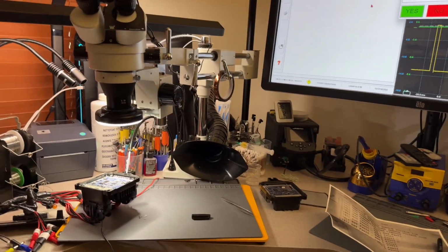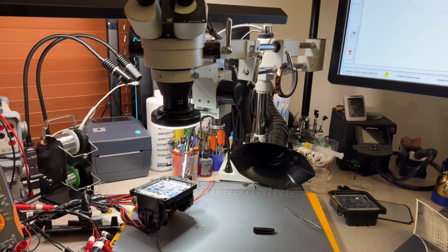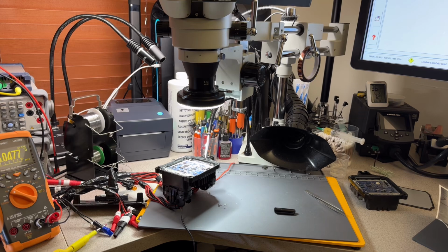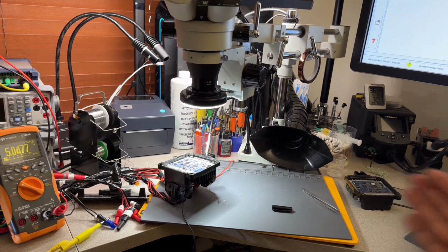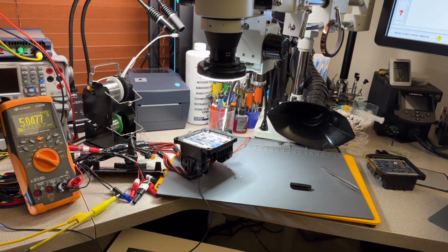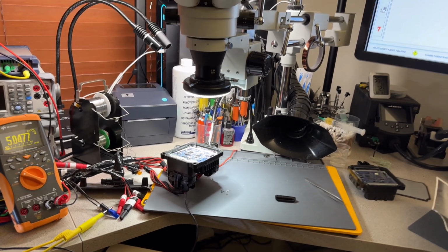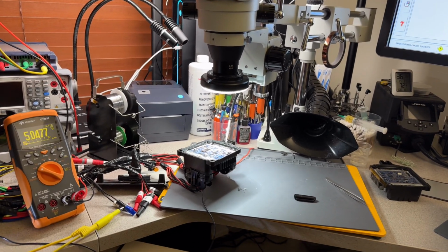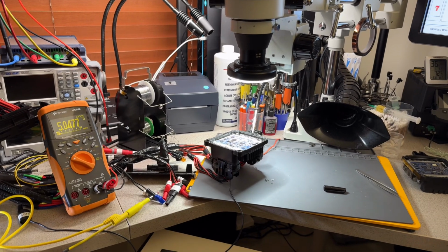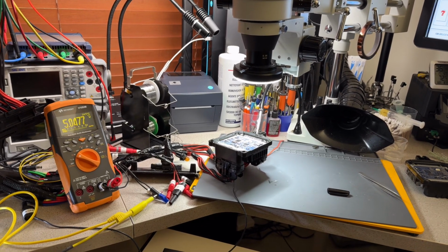So, David, your computer is good. Your problem is either on the harness or on the boat. I can show you the same, because at first I was running this test and I didn't erase the faults. I erased it, but with the computer running, and I had to do it with the computer off. So that was my mistake, and the reason I started to run the video.